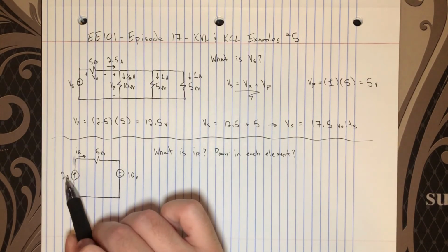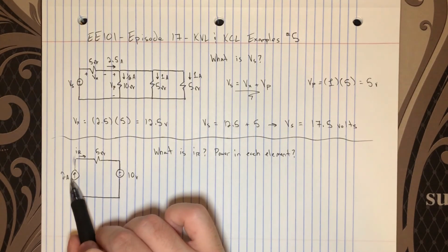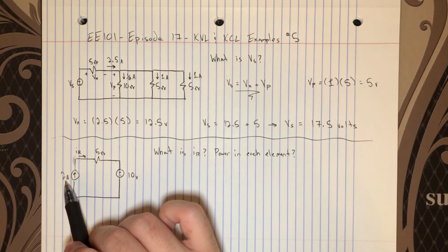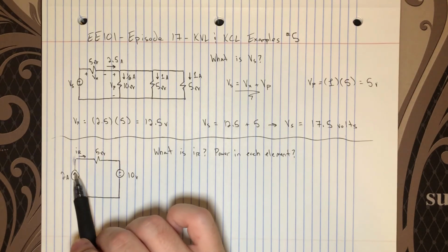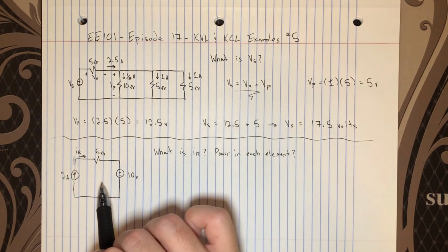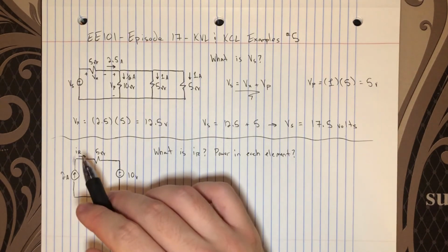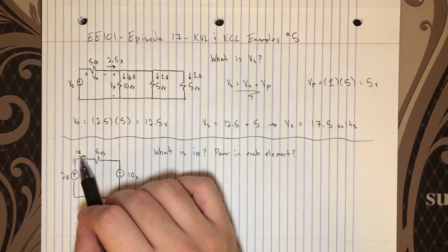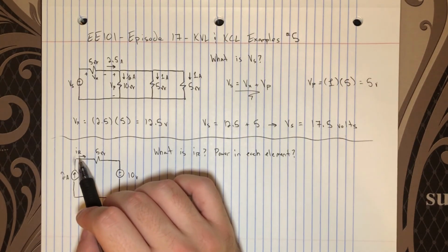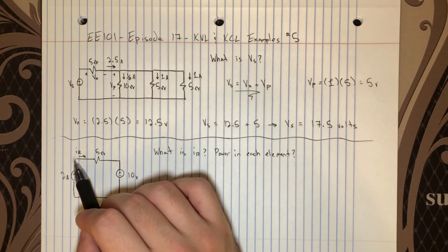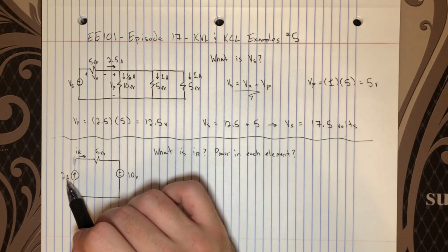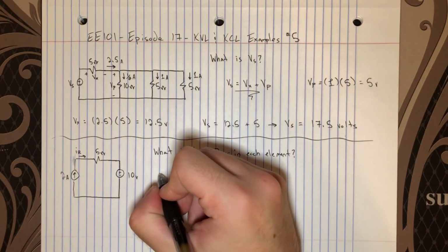This is an ideal current source. What this does is it forces the specified current, in this case 2 amps, to flow in the specified direction, no matter what is attached to it or the voltage across it. Which means, as drawn here, because IR matches the same current direction as the source, it's in agreement polarity-wise. IR is just 2 amps. So that is really easy.